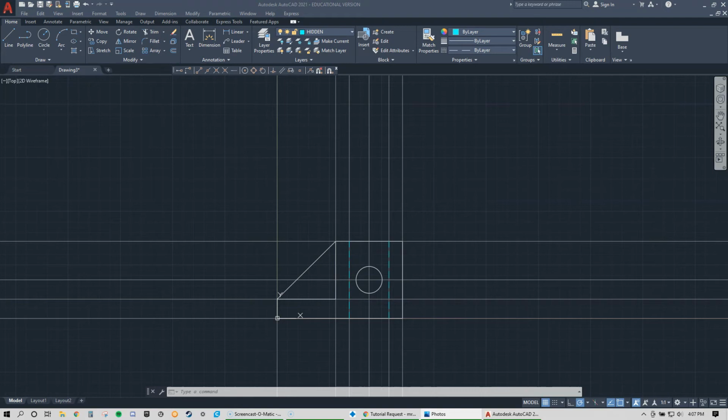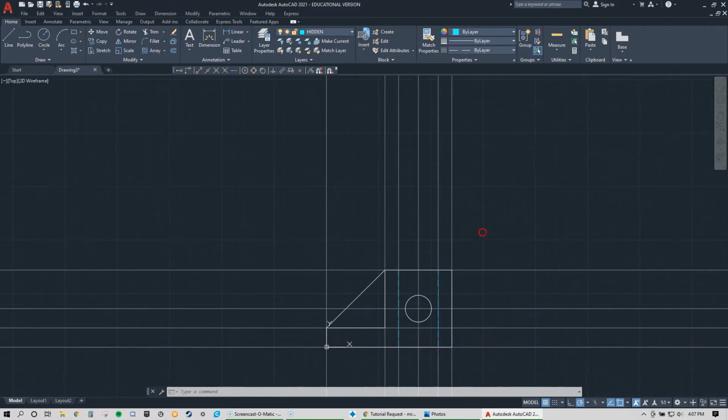Because the right side view is literally just a square with a bunch of hidden lines. The left side view is essentially a square, a few object lines, and a whole bunch of hidden lines. There's nothing I would actually use to dimension by one of those side views. I could dimension this whole part in its entirety with just 2 views, okay? So that's what we're gonna create. All right, if you need to create that 3rd view, I'm sure you can fix it very, very easy, okay?